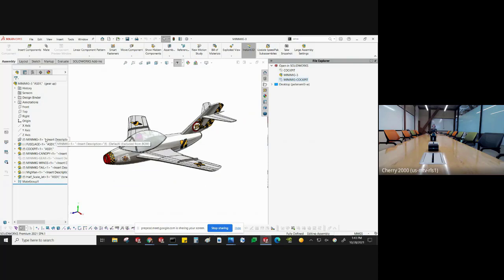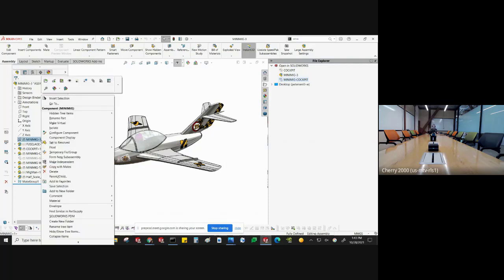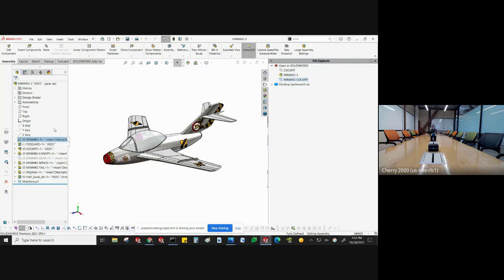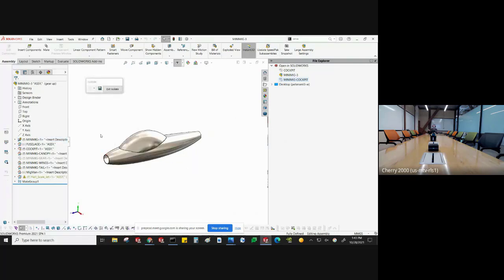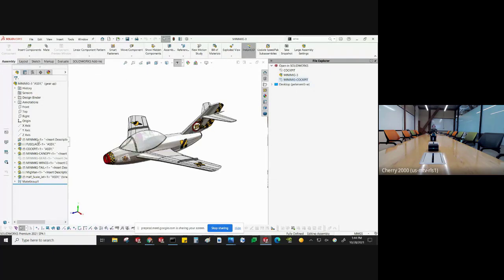Okay, here's something that I use all the time when I'm doing design. It's called an envelope. I don't know if everybody's familiar with it, but usually what you'll use an envelope for is a virtual part that's the geometry that you're trying to capture. So if I isolate the envelope that I've got, everything is built around this. And rather than putting this part into all the files, I just put it at the top level assembly, and I can see exactly where it is. And here's what envelopes do for me. They give me the 3D geometry, so I can offset surfaces, I can sketch on faces, I can use the geometry to convert entities and things like that.